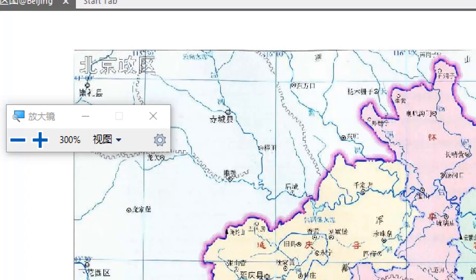For example, this point is 115 and 50, and the y coordinate is no, the y is 115, and the x coordinate is 41. So we can find the control points, input the coordinates, and do the registration.